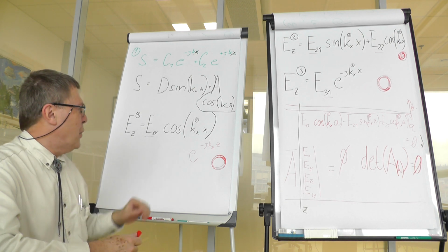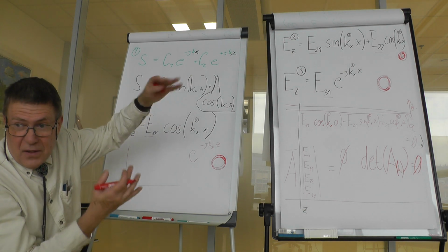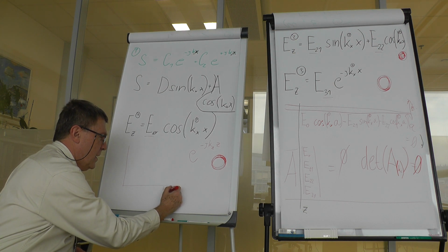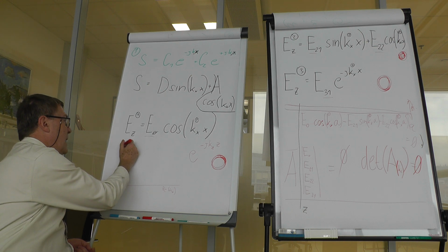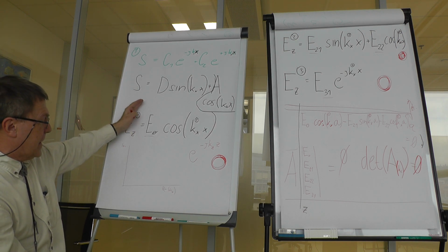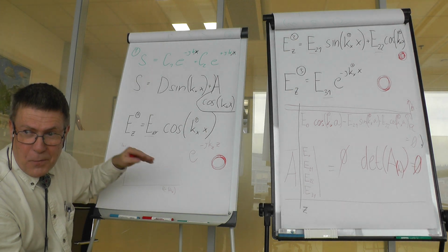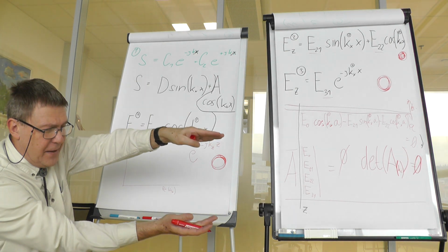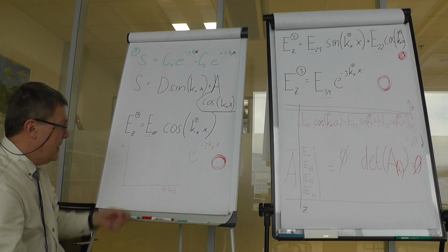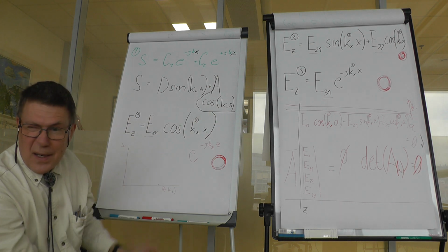There is also one point I would like to raise. If you plot the determinant as a contour plot for a given geometry and permittivities and so on, you would have the real part of the kz on this axis and the imaginary part on this axis. So this is affecting wavelength, this is affecting losses. For a waveguide that is without any losses, for the initial nice case of two ideally conductive plane parallel sheets, you would have a first zero somewhere here. Where here? Well, when the distance between those two walls is 1/2 wavelength.